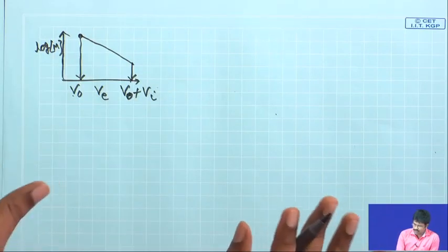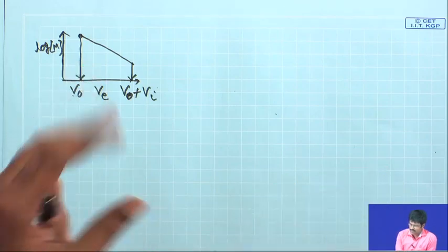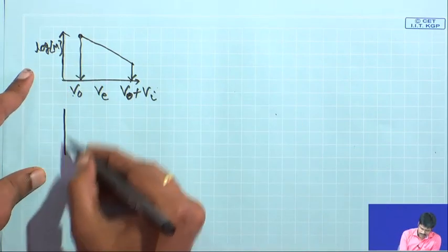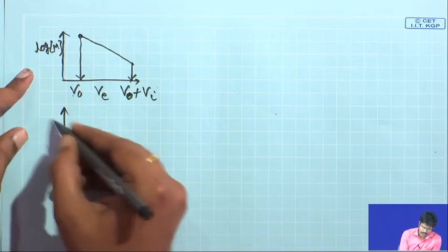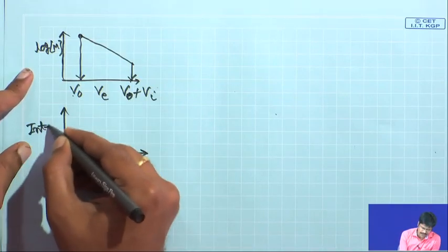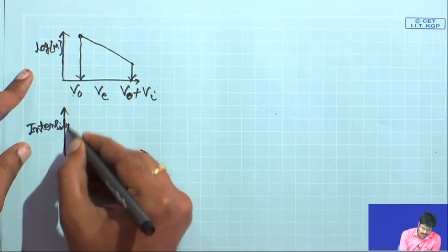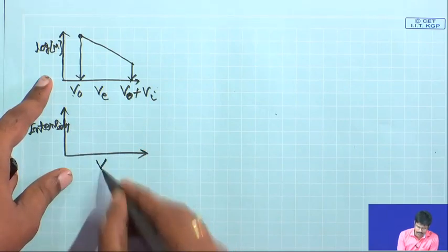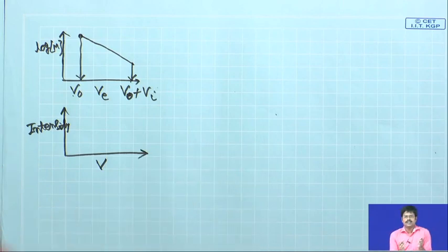Now, what you do is you construct a calibration curve. How do you do that? You have the detector response on this side, intensity, and you plot this intensity with respect to the elution volume, and you use standard materials of known molecular weight, fairly monodispersed, and you put them in the machine. So, you know at what elution volume or what time it is coming. That elution volume you can correlate with molecular weight, because you have this linear plot.